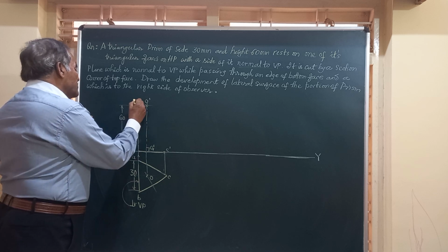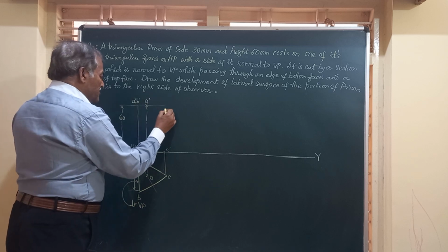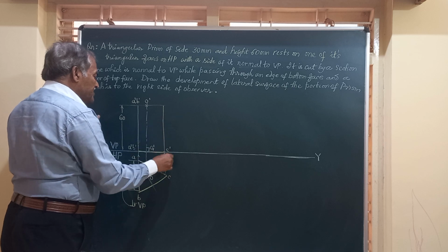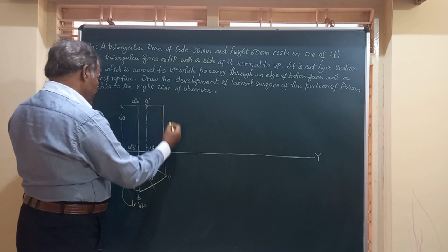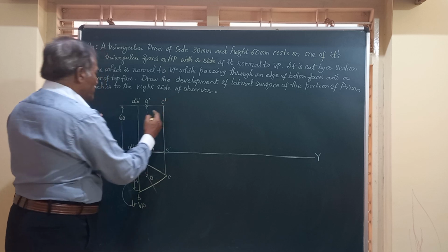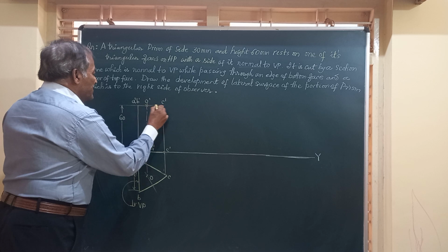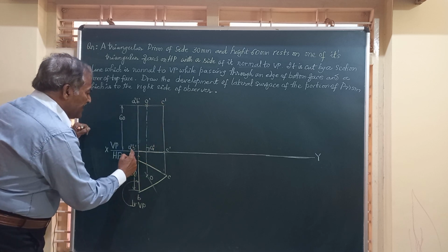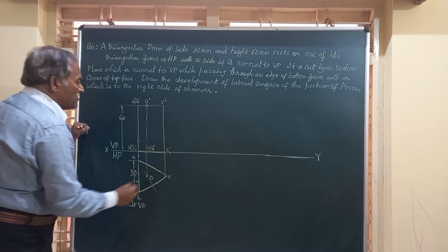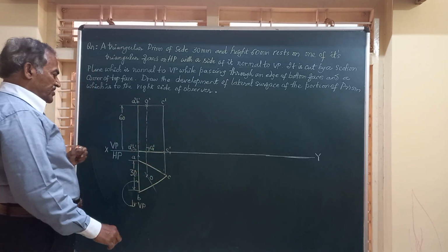So this is going to be A dash, B dash, and from here you draw another line upwards to a height of 60 mm, and this will be the point C dash. So we have got A dash, B dash, C dash as the top face, A1 dash, B1 dash, C1 dash, base of the bottom face, and O dash, O1 dash is the axis, friends.